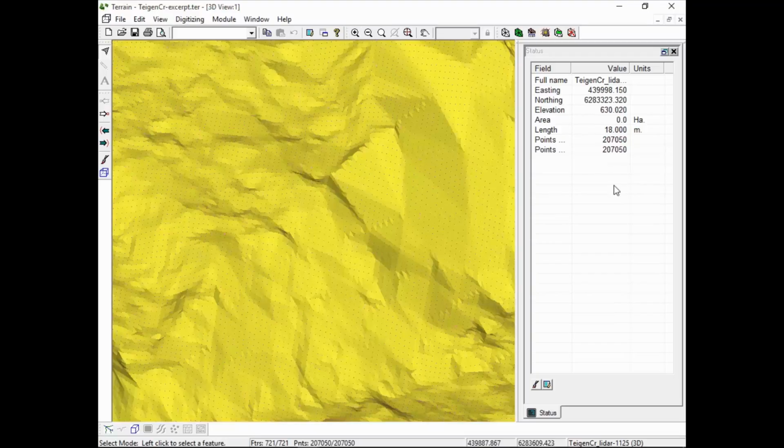Okay, there we go. So the points were sampled at 1 meter intervals, but what's that? That's a triangle. You can see quite clearly there's a triangle in the data set when you're looking at the shading of the surface. There's another triangle. Those triangles are between the real data points. So there's a data point there. Down here about 8 meters away, there's another one. Up here about 10 meters away, there's a third one. And that's the real data. All these dots in the middle were just interpolated. And these little zigzags that you see along the triangle edges are artifacts of the sampling.